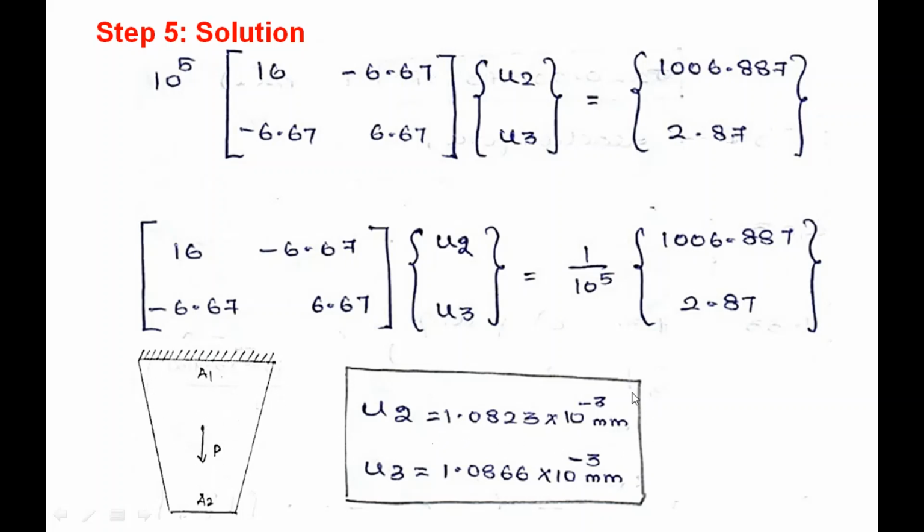Then the total load P is carried by this top portion, so that is why the deflection of the top portion is high. When you come to the bottom portion, element 2 has only the self-weight of this portion. Only this self-weight causes this small variation in the deflection. We have to know how to interpret the solution, right? The second element is subjected to only its self-weight, that is why we have a very small deflection value, which we have to understand.